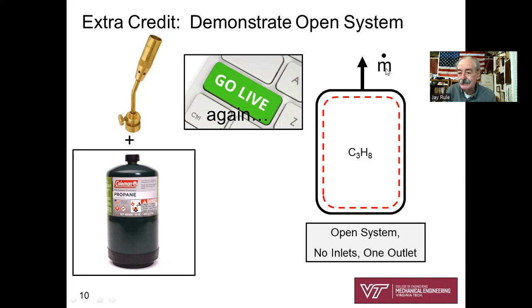That's not mass, that's mass flow rate. When we put a dot over things in this class, that indicates a rate. When I was doing the demo, you saw the propane coming out, being burned at some rate, some kilograms per second, a tiny little number, but it was a mass flow rate, M dot. So get that in your head. No formula sheet's going to save you in understanding what M dot is all about.